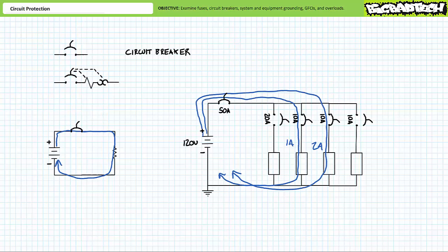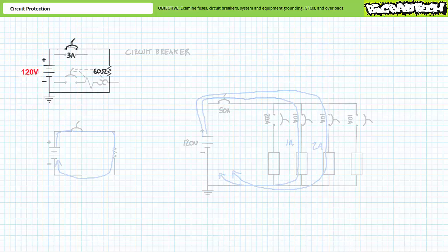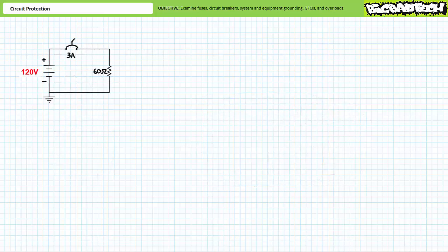As was the case with fuses, there's not a lot more to say about circuit breakers except this. Circuit breakers are reusable electromechanical devices designed to protect the system from high current. Fuses and circuit breakers do not protect operators from leakage current. More on this point in a moment. Before we discuss operator protection, let's briefly discuss system and equipment grounding, bonding, and equipment grounding conductors.